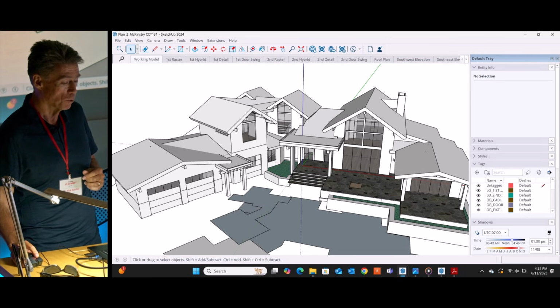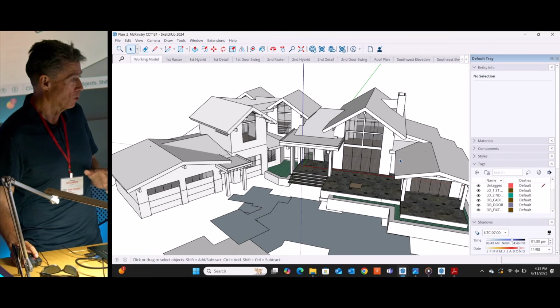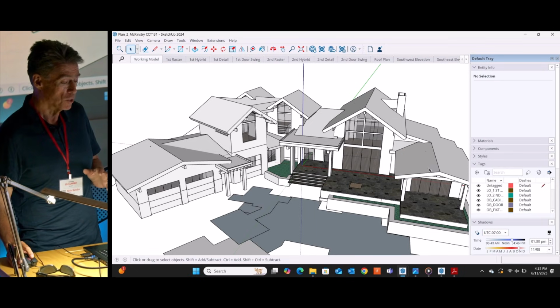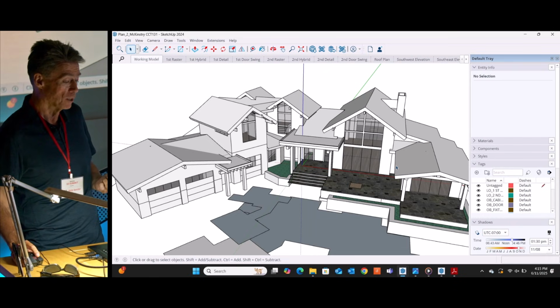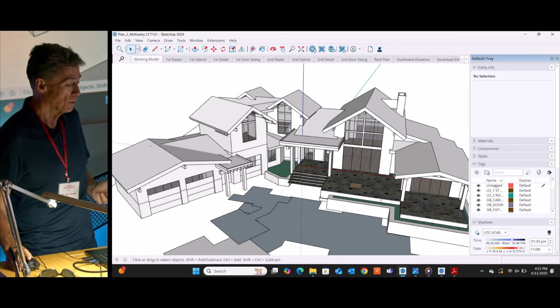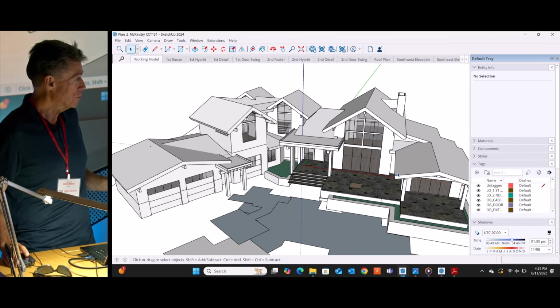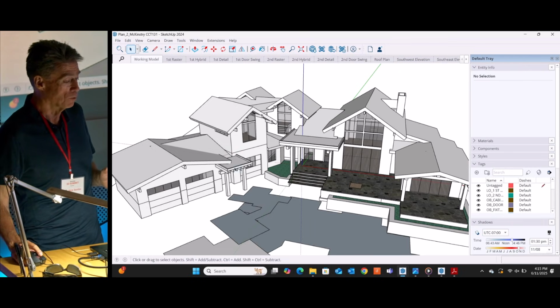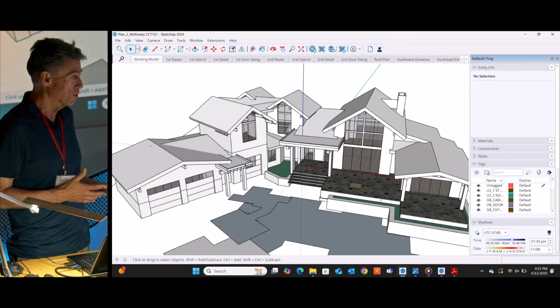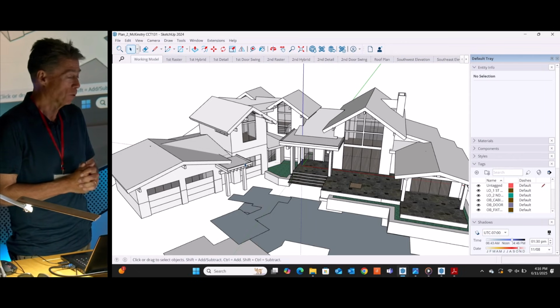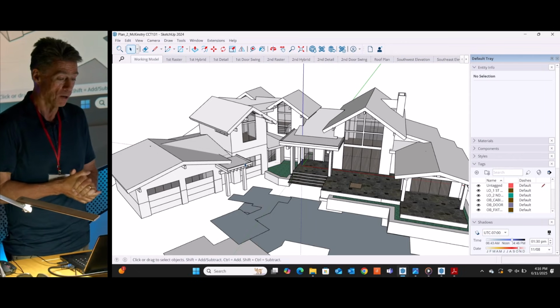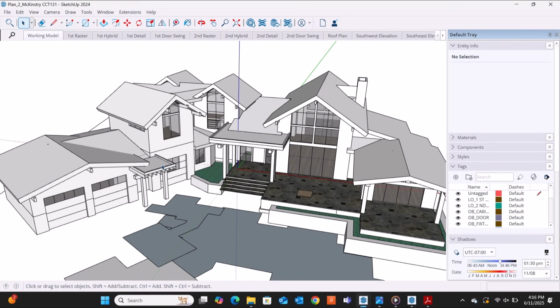For instance, on this roof, I expressed to the client, we're going to have to do some either snow retention or make sure this is composition shingle to help hold the snow. And then we actually run gutters in those areas with heat tape. And we'll have a lot of that through this house. Any of the flat roofs, we will usually drain with scuppers to an open end. We don't enclose them with a parapet because that has proven to cause major issues in our area, especially in heavy snow years like we had in 22, 23.